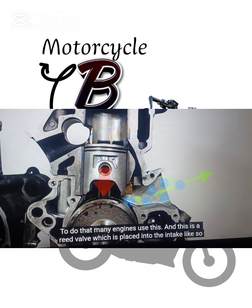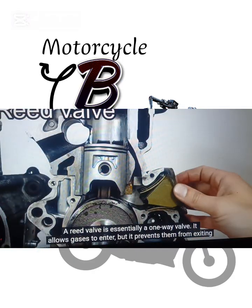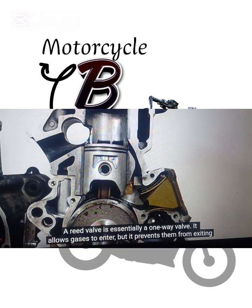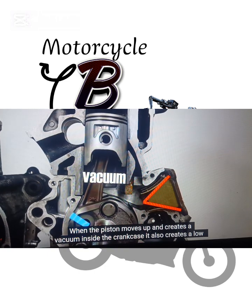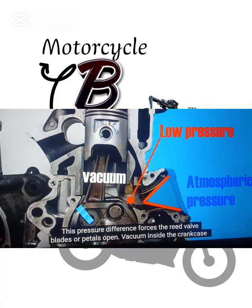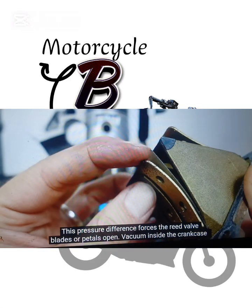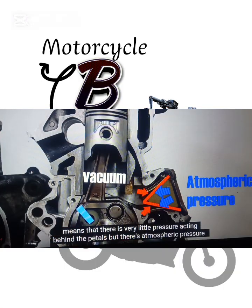To do that, many engines use this, and this is a reed valve, which is placed into the intake like so. A reed valve is essentially a one-way valve. It allows gases to enter, but it prevents them from exiting. When the piston moves up and creates a vacuum inside the crankcase, it also creates a low pressure zone inside the crankcase, while a high pressure zone remains outside in the atmosphere. This pressure difference forces the reed valve blades or petals open. Vacuum inside the crankcase means that there's very little pressure acting behind the petals, but there's atmospheric pressure acting on the other side of the petals, forcing them open.